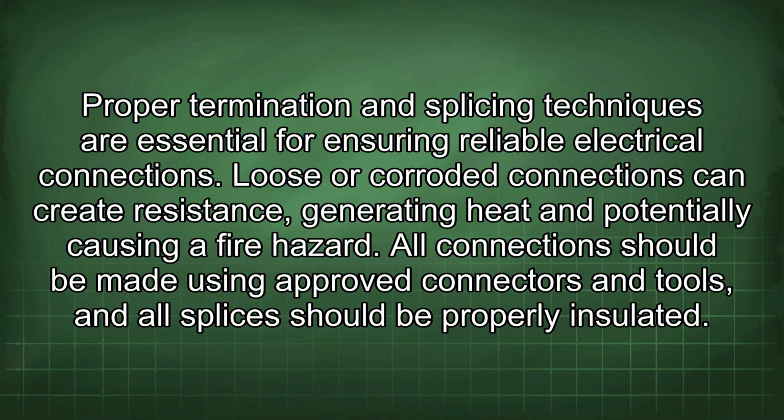Proper termination and splicing techniques are essential for ensuring reliable electrical connections. Loose or corroded connections can create resistance, generating heat and potentially causing a fire hazard. All connections should be made using approved connectors and tools, and all splices should be properly insulated.